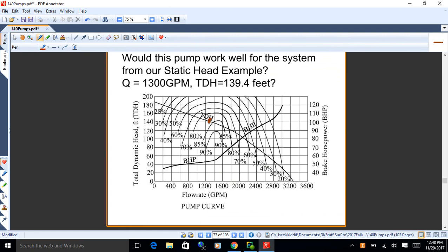So, what's that? I'm sorry? Trying to get that X to basically go over where your losses are. Yeah, you're trying to get the two curves to match each other in a place of efficiency for the pump that'll do the job you want done.